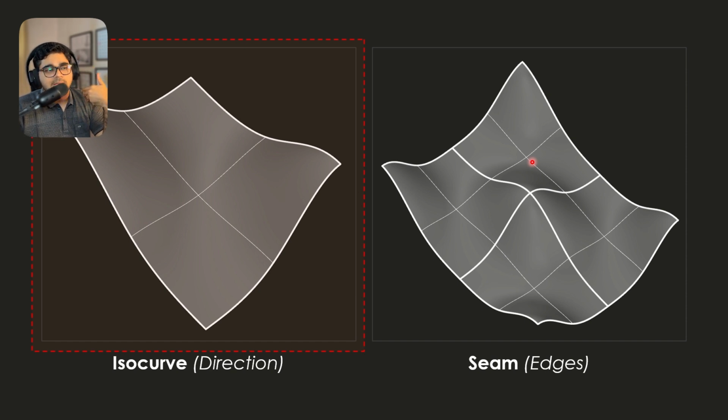Because you can't directly push all of these patterns onto multiple surfaces, and if they are not really designed together, they will not look nice. So let's stick to one particular surface. And now we know that we will manipulate the surface using control points. So let's say while moving the control points, the shape of this U and V direction becomes something like this, versus something which is very orthogonal. This becomes S-shaped.